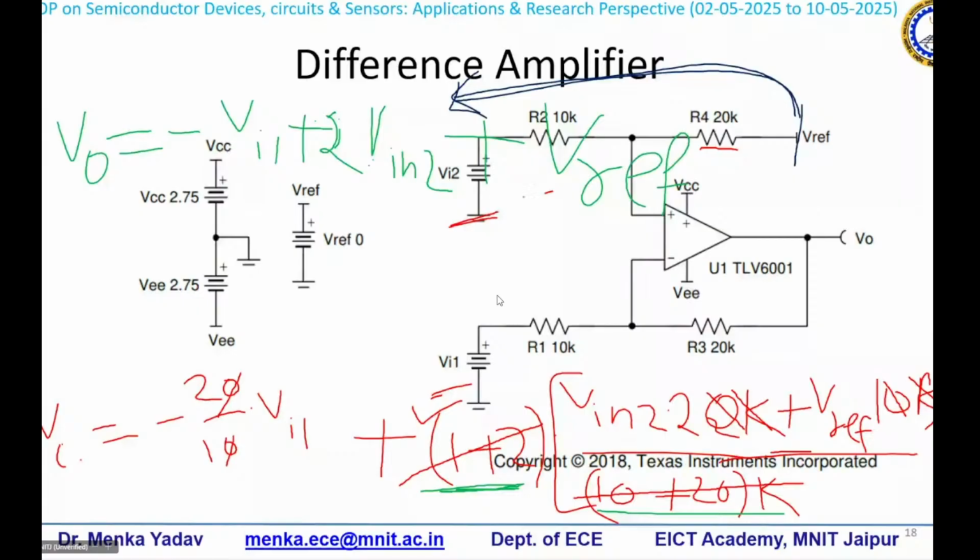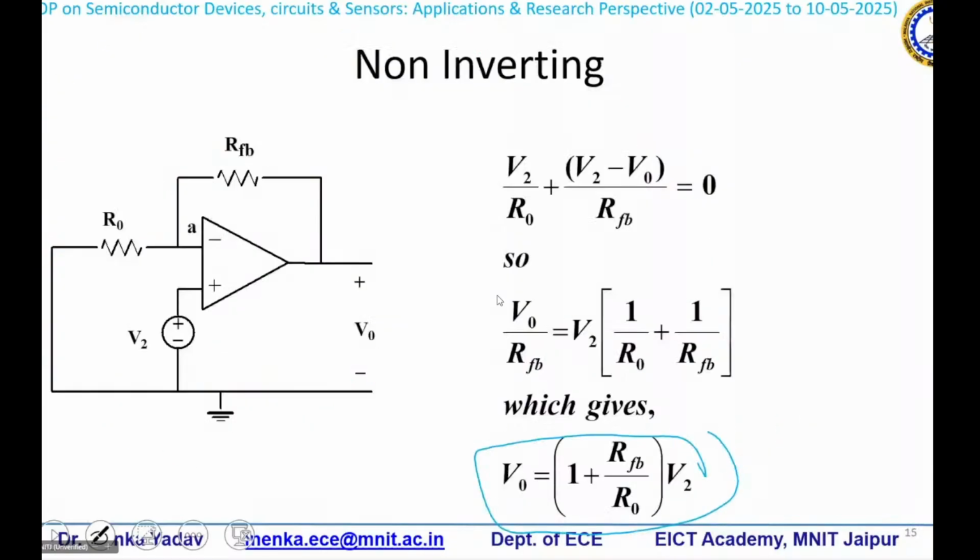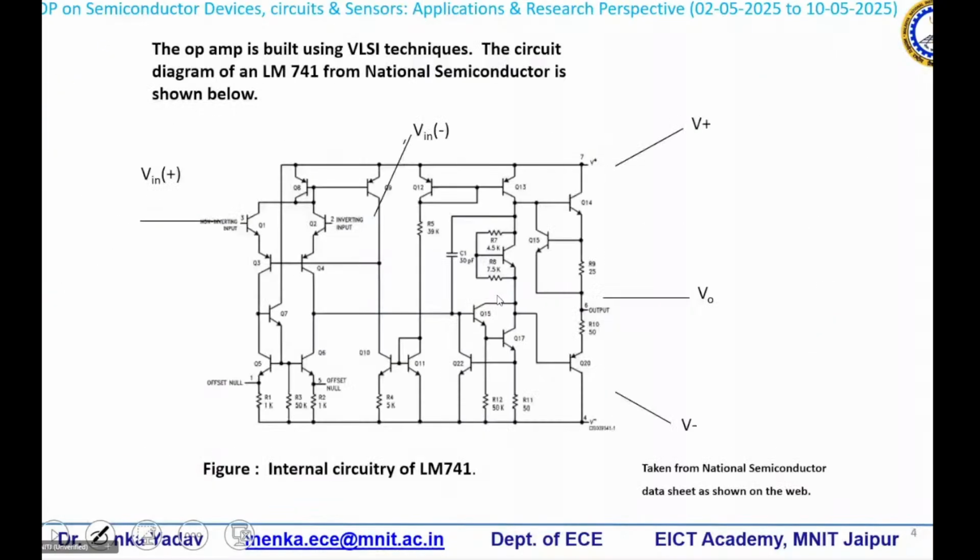So for this type of circuits, how are these circuits designed? First of all, I told you yesterday that this op-amp is prepared by the different MOSFET circuits or BJT circuits, which are taken at the input. These are taken as the difference amplifier. What is the difference amplifier? Let us take it. It can be represented in this way. Difference amplifier means symmetric devices will be taken up and the output will be taken from the opposite branches. It is clear from this one, right?